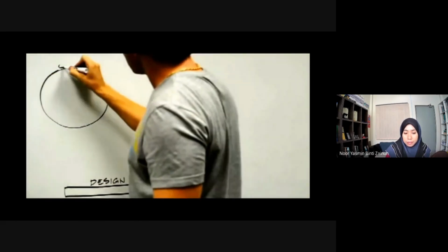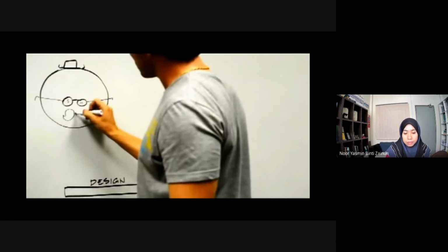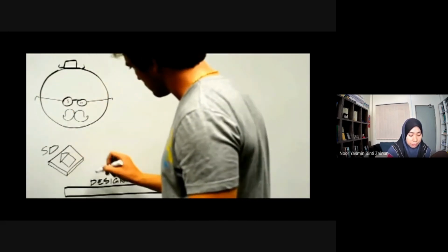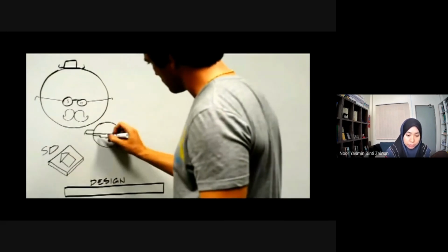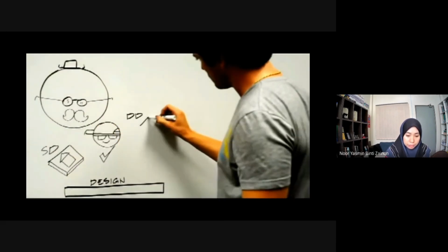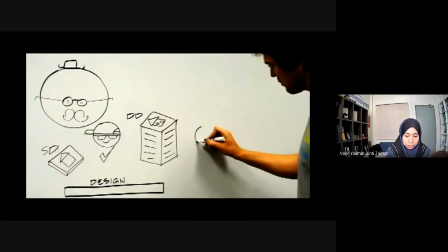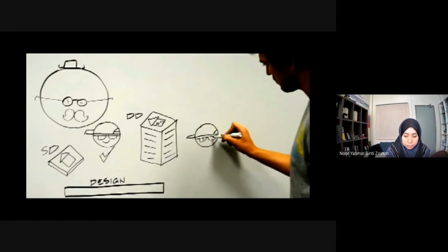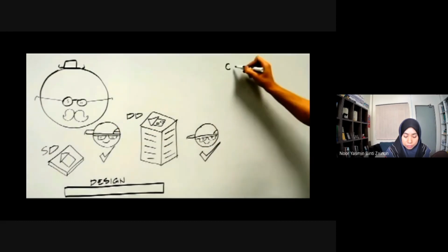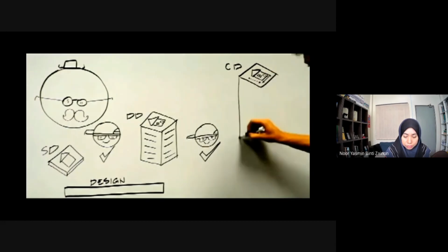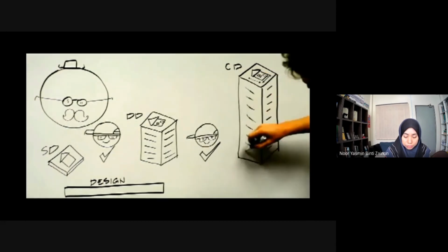and construction. During the design phase, the design party will first carry out a schematic design, or SD, the goal for which is to arrive at a clear concept. After the owners review and approve, the design entity proceeds to more fully develop the design concept and preliminary specifications during what is known as design development, or DD. At the end of the design phase, after yet another review and approval of the owner, the architect prepares final drawings and specifications, also known as contract documents, or CDs.